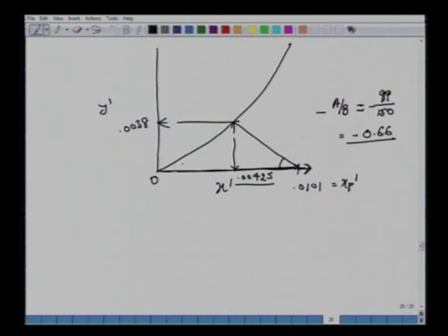I said earlier, you can work mathematically, writing down the equations. Material balance for one stage, species balance for one stage, with two incoming streams and two leaving streams, with the constraint that the two leaving streams satisfy these equations, or their coordinates y dash and x dash lie on this equilibrium curve. So you can solve mathematically as well if you know the equation for these data. But we said that generally all these data are in tabular form, so it's more convenient to work on this graphically. All right. So from this we read 0.00425. So how much nicotine have we removed?